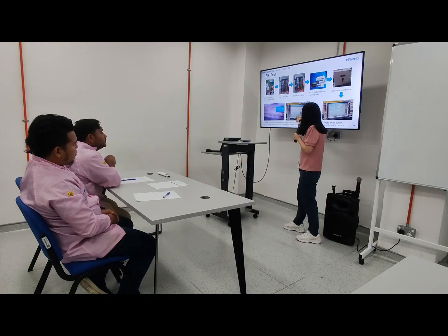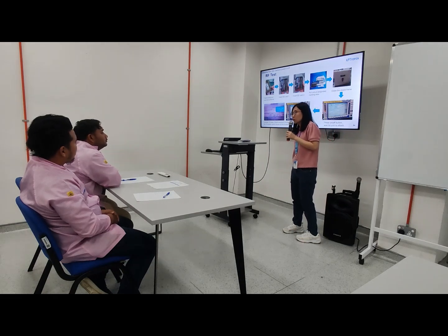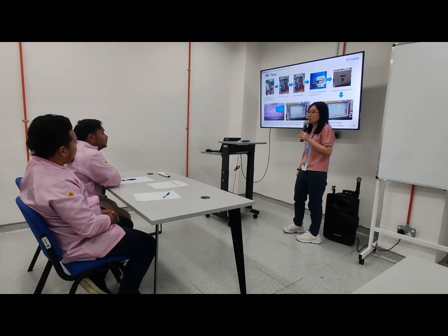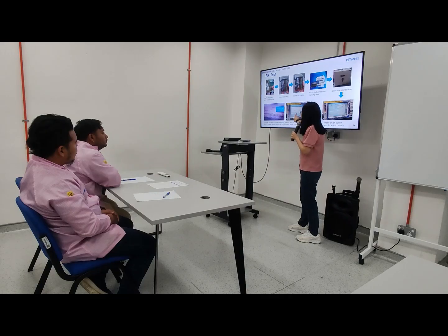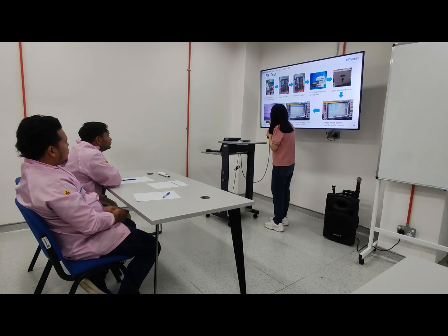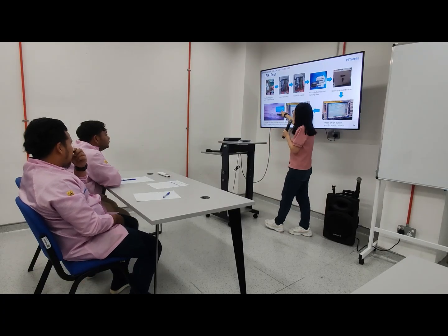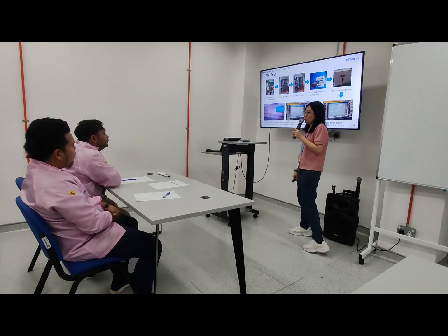If there are sudden peaks, this should be something abnormal with the board. And maybe we need the PE to troubleshoot what is the main problem causing it. Then we'll check the TX power, ensuring all are between 11 to 20. The value must be almost the same, between 11 to 20. Yeah. Okay.